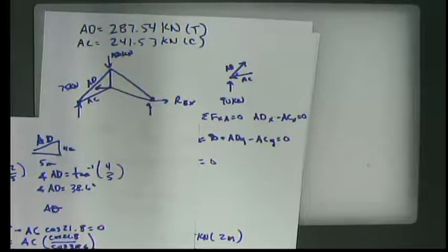But what also happens is that if you have this kind of truss, the house is always trying to go like this or like this. So right here where the wall connects up to the truss or to the roof structure, you also have an incredible load. So you have to reinforce it here so it doesn't splay outward, and you have to reinforce it here so that the walls don't splay outward. It's a lot. They call it live load. It's not really an engineering term, it's more of a construction term. But there's a lot of motion in loading something like this.